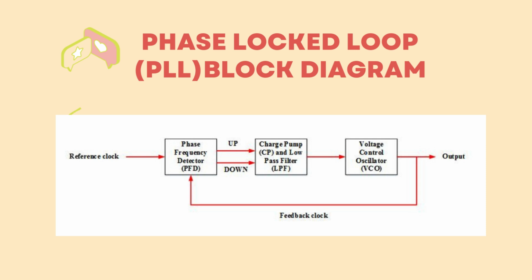The first block, phase frequency detector, or PFD. This crucial component takes two input clock signals, our reference clock and the VCO feedback clock. Based on their phase difference, it generates UP and DOWN output signals, which act as instructions for the next stage.